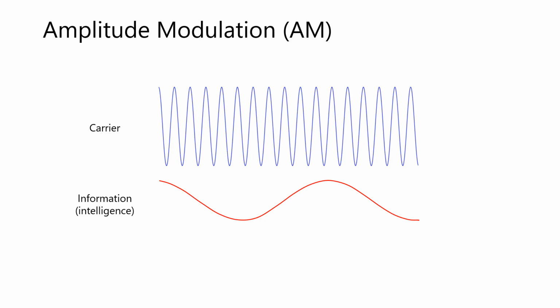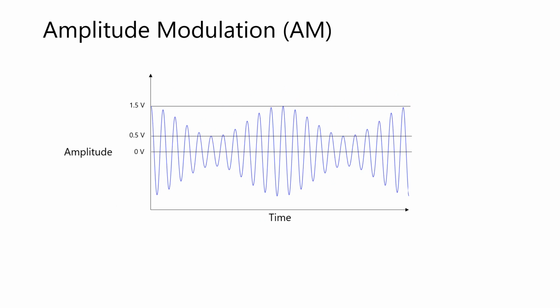shorter in length. Here we see an AM waveform in the time domain, much like the display of an oscilloscope. The information is outlined by the red lines. Notice that it appears in both the upper and lower sides of the carrier, known as the sidebands. The amount of modulation, known as the depth of modulation, can be calculated with the following formula.